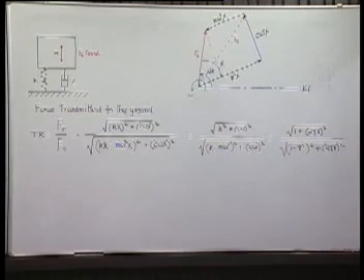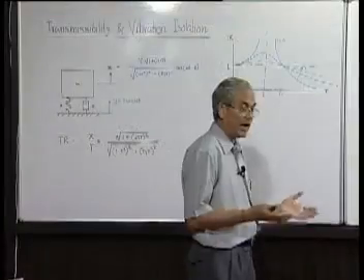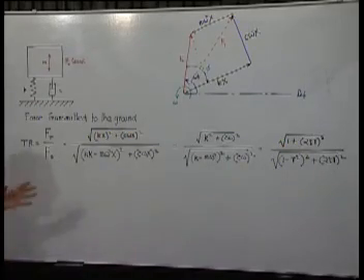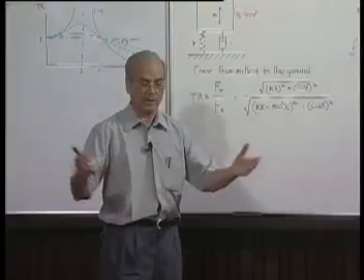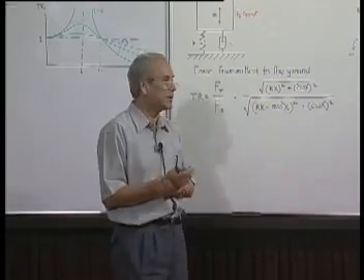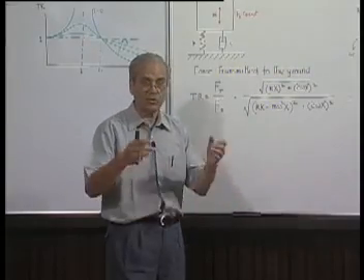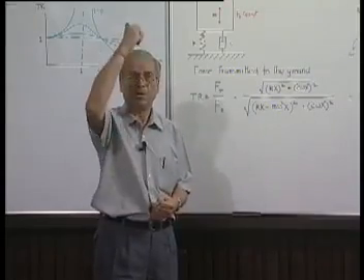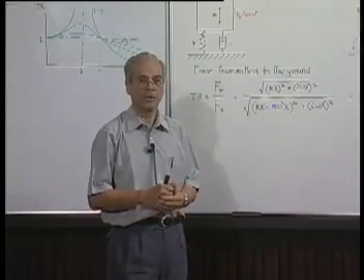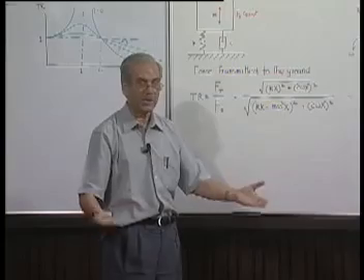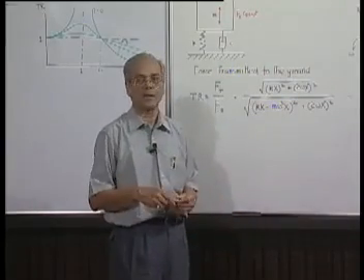So, therefore, it is a very important result of the study of vibration that we can isolate systems and machines from the environment, so that neither an unwanted disturbance comes to our system when we are handling very precision experiments, or the ground does not get too much disturbance from the machine on which I am working, suppose a very heavy forging machine or machine tool which is generating large force, then a smaller amount is really going to transmit to the ground. So, that ground will have lesser vibration produced by this transmitted force.